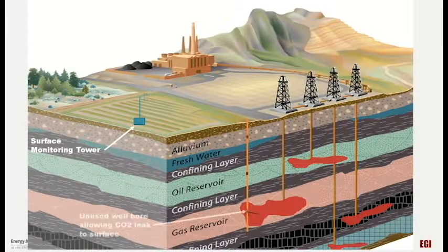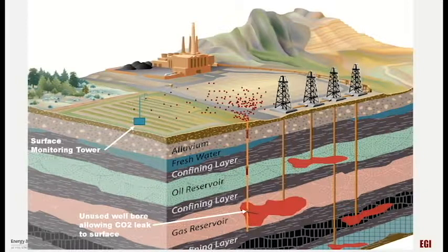Suppose an old wellbore is allowing some of the trapped carbon to make its way to the surface. Theoretically, a large enough leak should be detectable in elevated surface CO2 levels. Leaks may exist as carbon makes its way up and out old wellbores, unidentified faults, or other unknown reasons. By using equipment detecting carbon concentrations in the air, and by monitoring air movement above carbon sequestration fields, we hope to be able to detect, locate, and quantify any leaks from the sequestration field.